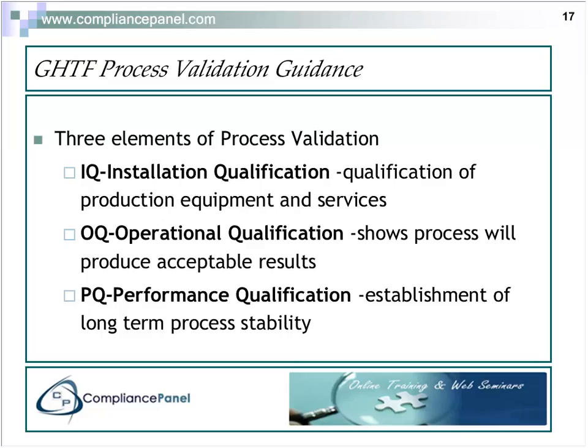The third and final phase is performance qualification, and that's the step where we establish long-term process stability. We're going to run it all shifts, all days, the way the process would normally operate. And we're going to demonstrate that it will produce product that meets the requirements day in and day out.